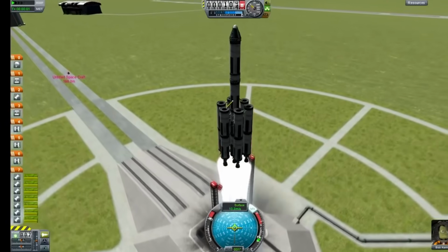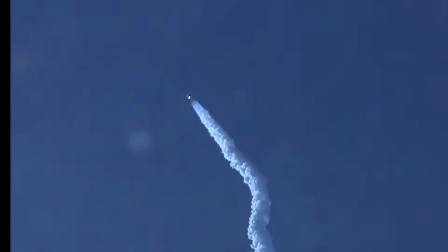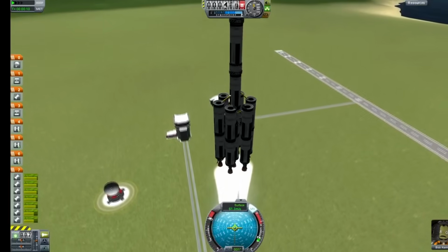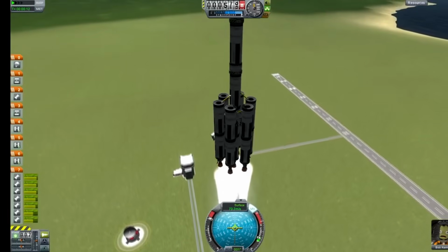But the idea is if you have something like the Falcon Heavy or the Delta IV, right? You've got three boosters there, and they burn in sequence, and the middle booster burns typically at 70% throttle, so that when the outside boosters use up all their propellant, it still has like 30% of its propellant left. Now, the idea with asparagus staging is instead you have pipes that feed fuel from the outside boosters into the central booster so that it's always at 100%.